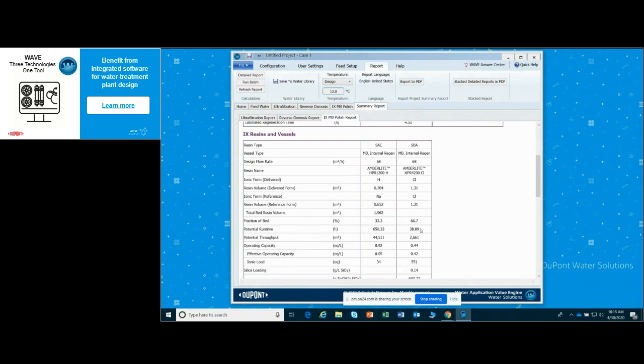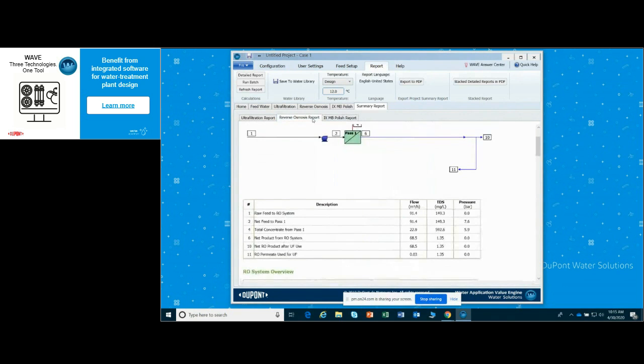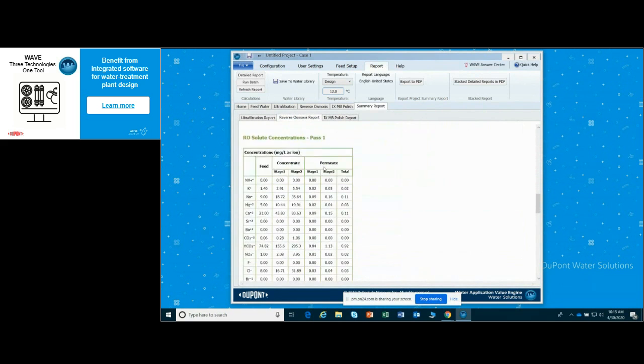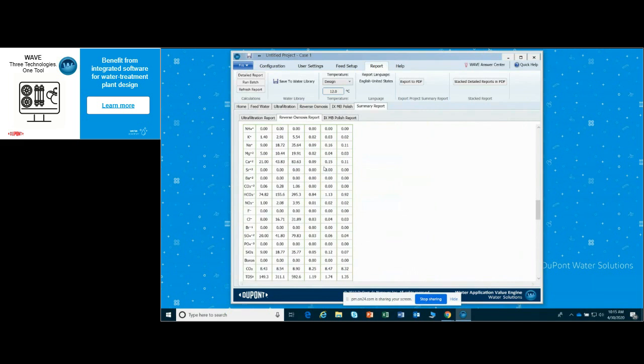Do you think we could take a look at the RO effluent just to see if CO2 might be a driving factor of that low run length on the anion resin? And if so, maybe we could do something, maybe just show one of the methods for mitigating CO2 out of the RO, either with a degas or by another means.